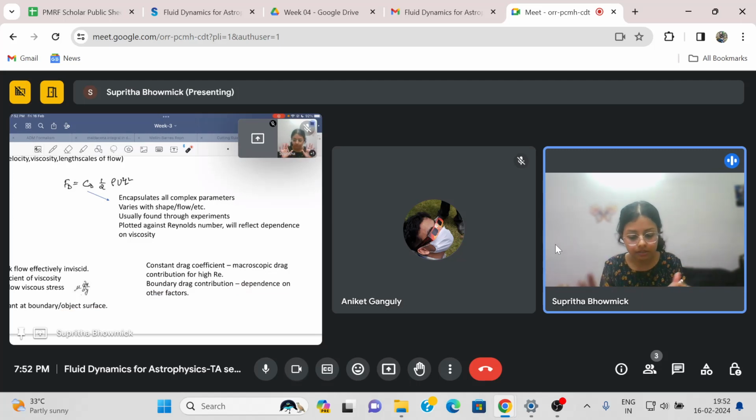So my point is, I'm using this relation for drag force, where it has a U squared dependence, L squared dependence. And I'm using this because CD is now dimensionless. The relevant dimensionful parameters of my system are rho, U, and L, and I have to construct a term which has dimensions of force from these three quantities.